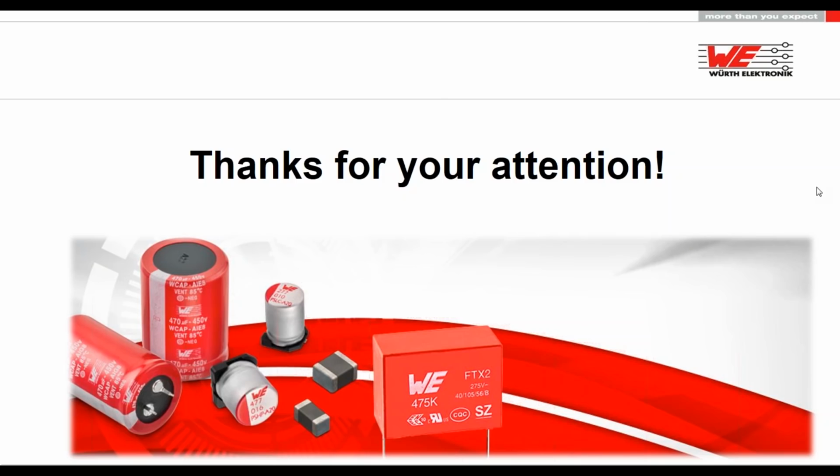Yes, there's also a question about the microphonic effects, how to suppress them. That's a good question. For suppressing the microphonic effects, if you want to stay with the same cap, the only thing you can possibly do is maybe add a resistor to change the impedance curve. This can possibly help to change the applied frequency, but if you do not change something at the input filter, if you, for example, have this at the output filter, you have to change the input filter to maybe change something.